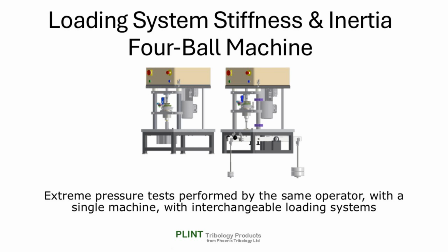Load was calibrated against a load cell inserted between the lower specimen carrier and the machine's spindle, ensuring that the static load with both systems was identical. It therefore seemed reasonable to assume that any change in tribological response could sensibly be attributed to the different loading mechanisms.